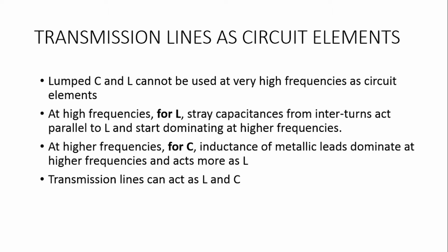Similarly, at higher frequencies, if we are considering a capacitor, the metallic leads can cause inductance at very high frequencies, and the inductance value will increase for very high frequencies. So because of these reasons, lumped capacitors or inductors are not that effective for operating at very high frequencies. So transmission lines can be used as inductors and capacitors. We will discuss that.